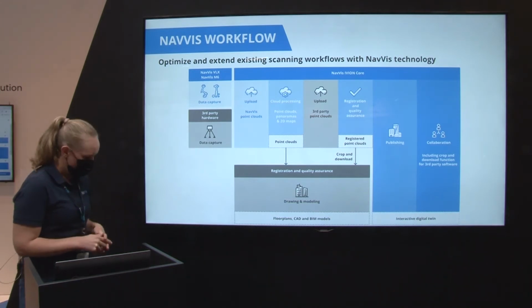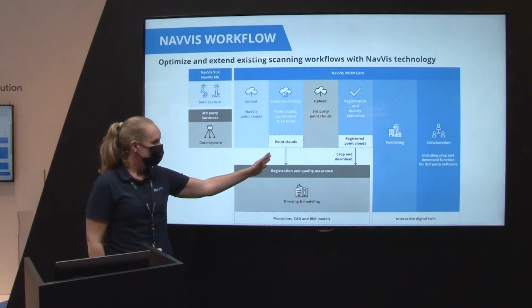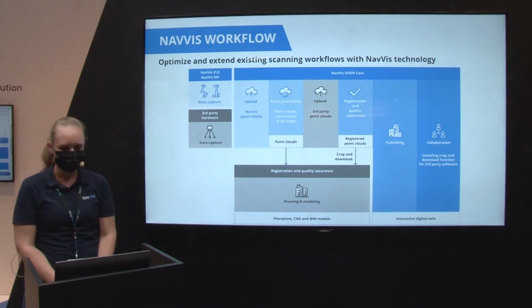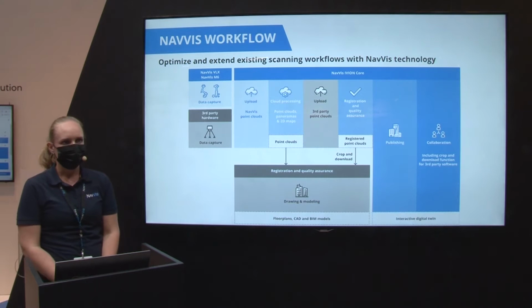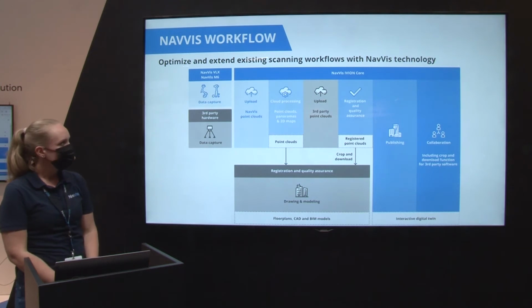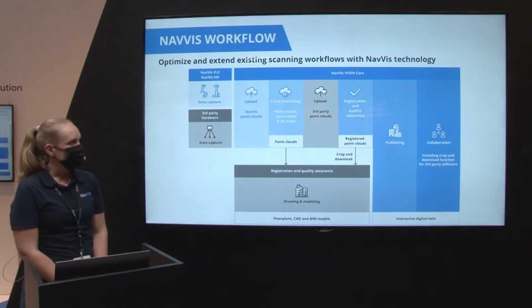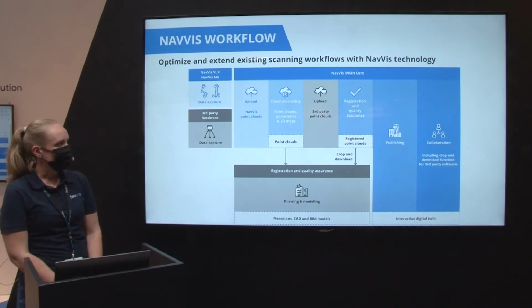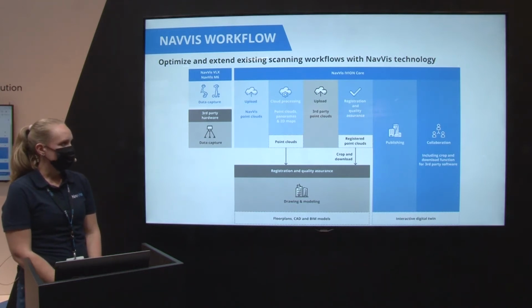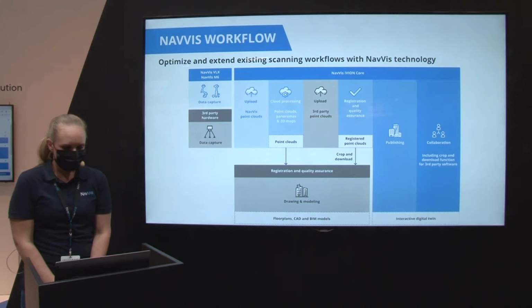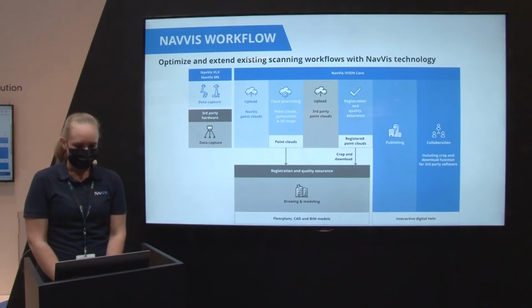And either you can now already download the point clouds and keep on working with third-party software for registration or quality assurance, for example, or you can, of course, also import into BIM software to draw and model on that data. But you can also stay in the NavVis Ivion Core world if you like and just upload third-party point clouds additionally to the NavVis point clouds, register them, do the quality assurance in NavVis Ivion, and then export the registered point clouds using the grab and download function. And again, of course, then use third-party software.